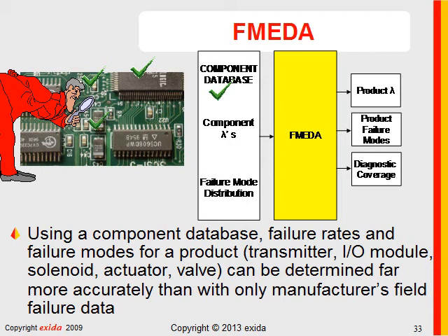We look at every capacitor and look at every failure mode of these components and ask the question, how does this impact the safety function of the device? It's an extremely detailed and systematic procedure, but allows one to predict product failure rates, product failure modes, and diagnostic coverage, even on brand new designs.